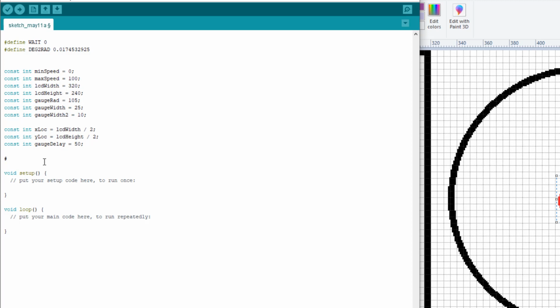Now, at this stage, this is where we need to include the M5Stack, if that's the board that you're using. So we're going to do m5stack.h. If you are using the TFT_eSPI library and you're using another graphics library like the GFX library for your specific display, then you would also need to include those as well. Again, this is why the M5Stack makes this process so much easier, because it simplifies it and it already includes the Sprite.h, which is again an adaptation of the TFT_eSPI that's in the description.